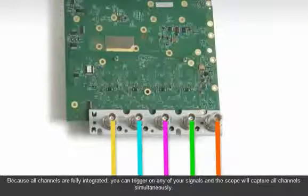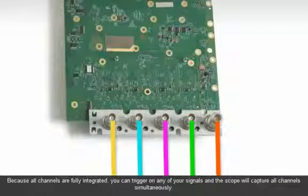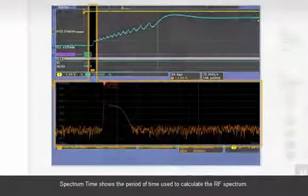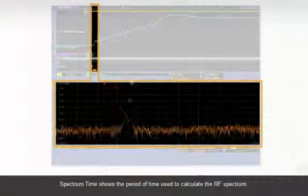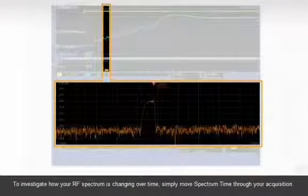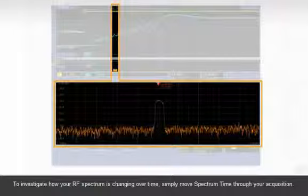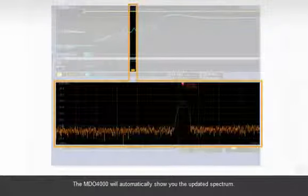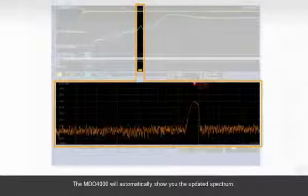Because all channels are fully integrated, you can trigger on any of your signals and the scope will capture all channels simultaneously. As a result, all signals are time-correlated for accurate analysis. Spectrum time shows the period of time used to calculate the RF spectrum. To investigate how your RF spectrum is changing over time, simply move spectrum time through your acquisition. The MDO4000 will automatically show you the updated spectrum.